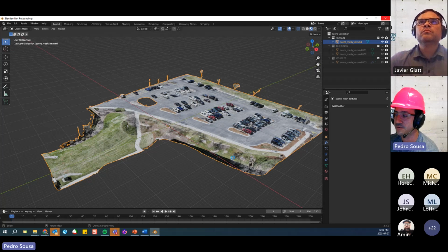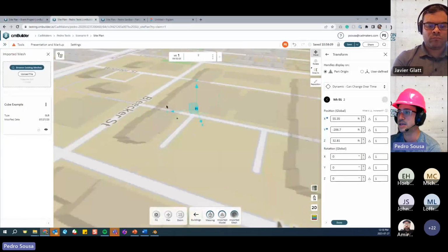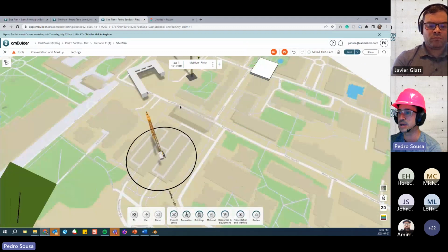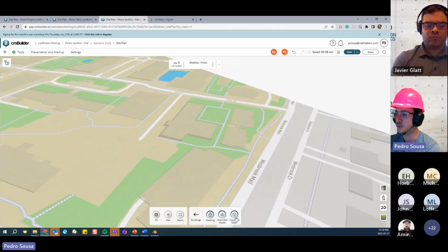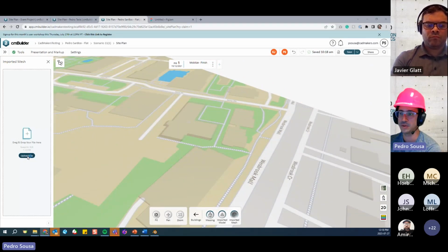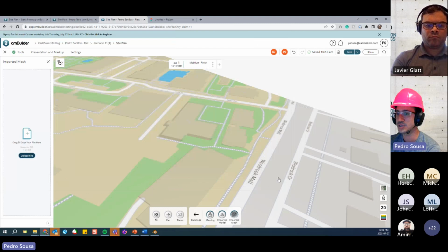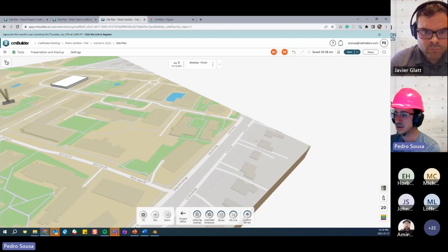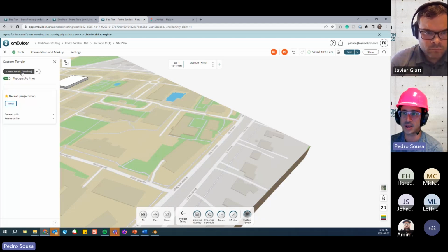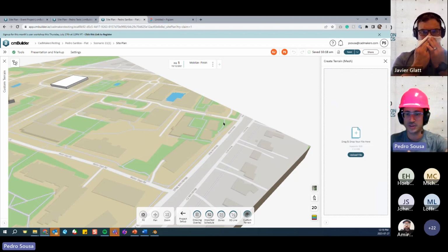Of course, this one over here, I didn't finish the processing because it would take me some time to separate everything. But basically, what you can do now is if you go into cmBuilder, I'm going to take any random scenario over here, and I can go into my buildings, import a mesh, and then upload that file that I just created, this one. This is going to take some time because the file is quite big. But once I imported that file, if it's representing just my terrain, I could come here in my project setup, click on custom terrain, click on terrain, create a terrain from a mesh. I would select that mesh and then my terrain would fit to that elevation.